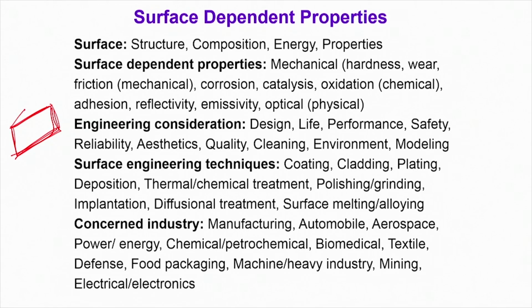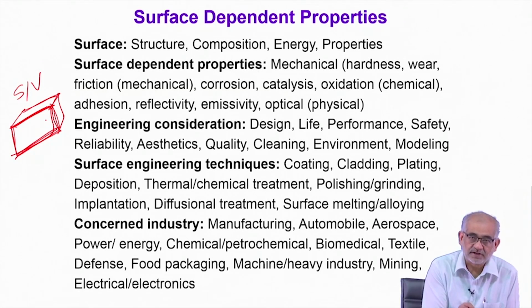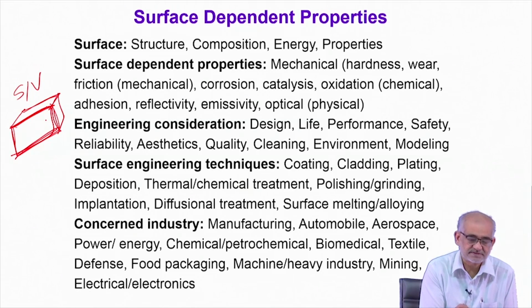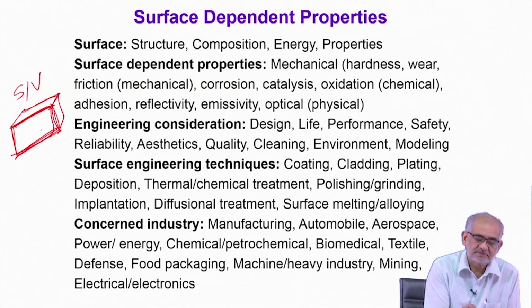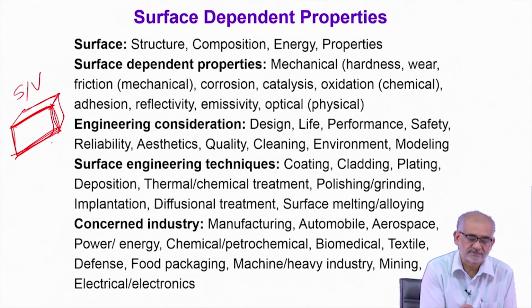So for a three-dimensional solid, we certainly will have certain external surfaces or so-called solid vapor surfaces, and this is where the coordination, or the surrounding atoms or ions or molecules, the species basically, the environment, is going to be different. So there will be at least 1 degree of freedom for any atom located at the surface compared to an atom which is in the center or in the interior of the solid.